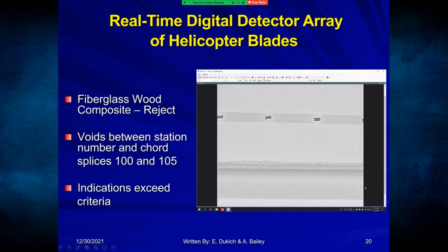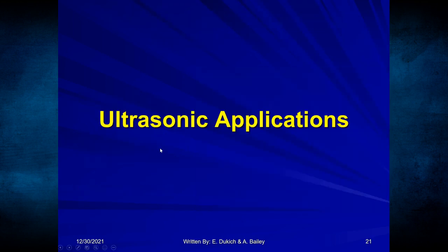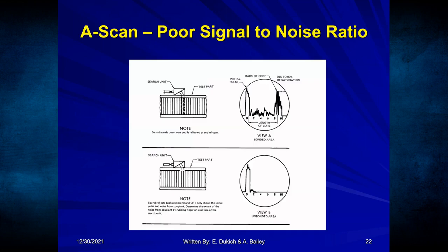So now, stand by one moment. All right, let's go to the next slide here. So now for ultrasonic applications, we talked about radiographic applications, and you can see that we can tell you where the flaws are, but we cannot tell you how deep they are. So the wonderful thing about ultrasonics is it can tell you where the flaw is and the depth of the flaw.